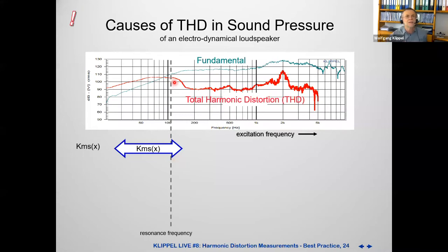Why? We need displacement, and we only have this in the base region. From the BL, it's almost the same result, but we see a little bit more at higher frequencies. That's because at higher frequencies, the BL distortions are decaying at a more shallow slope, not as steeply as the stiffness. Why? Because current is also involved.